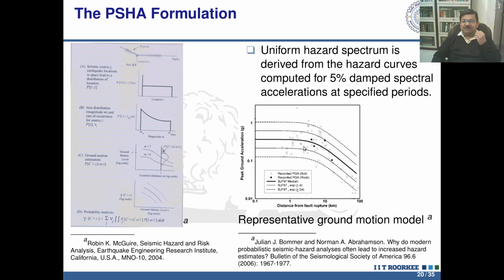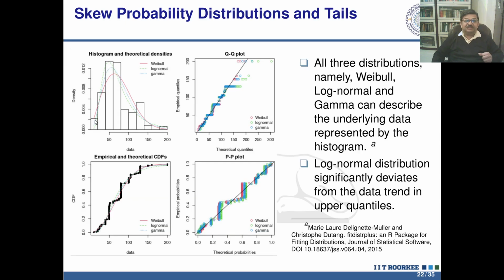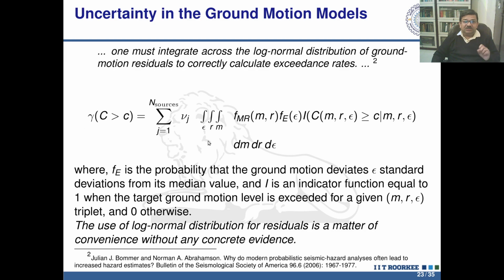And then if I try to include that range in our calculation, I am effectively considering, because this is log normal, an open-ended distribution. So even a small magnitude earthquake, which is not damaging at all, will have some finite probability of exceeding a certain ground motion threshold, and it will contribute. Right? So this value actually depends on how much epsilon I account for in this integral.